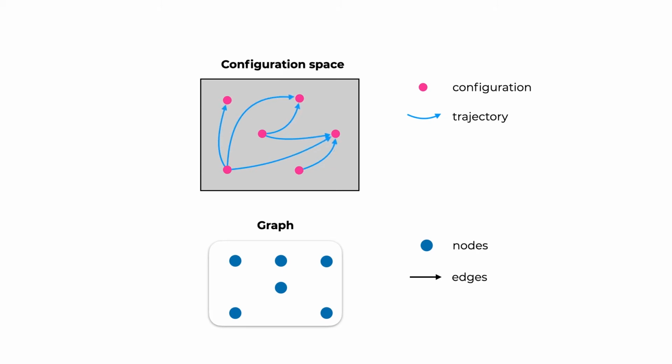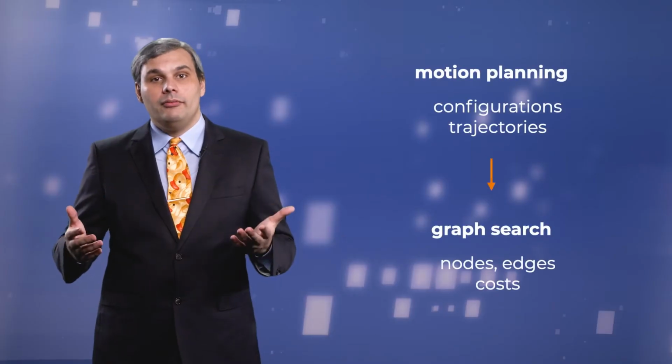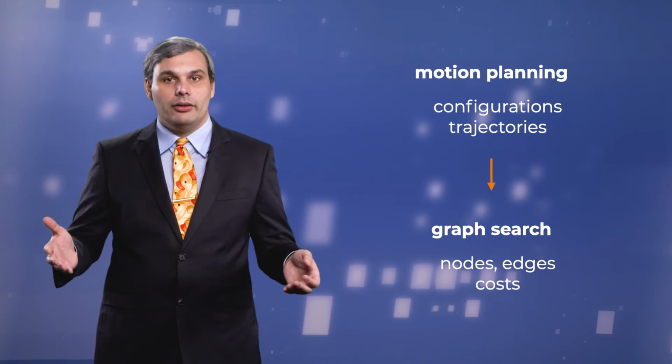The edges between nodes represent possible motions that the robot can use to go from one configuration to another without touching obstacles. The edge labels represent costs. For example, we could take the cost to be the time it takes to go from one configuration to the next. Of course, we will not put in the graph nodes that correspond to configurations in which the vehicle collides with the obstacles. Once we have the graph, we can apply a generic shortest path algorithm.